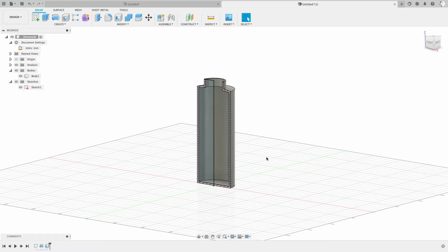And what I'm trying to talk about is that in CAD, you want to start with very basic steps and explore proportions first. So that's what we did here. Basic sketch, this revolve, and then we quickly shelled it to see, does it work? And then step by step, we start adding details for it.